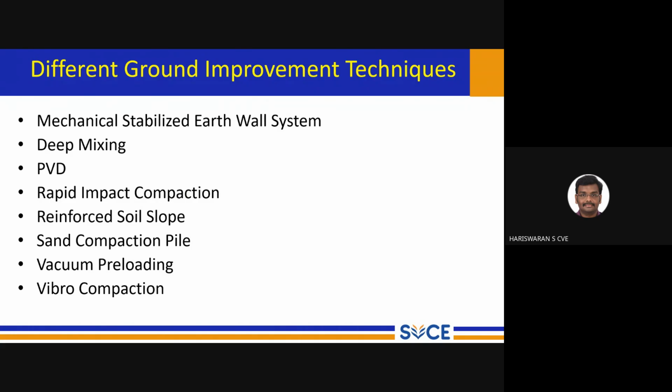For example, if we are going to construct a structure on a particular area of soil, it will transfer some amount of stress. The same stress can be predefined and applied before the construction itself, like placing very large concrete blocks over the soil. That load slowly compresses the soil because of the applied static load. Based on the stress applied, the water present inside the voids of the clay slowly dissipates outside. This process we call consolidation.